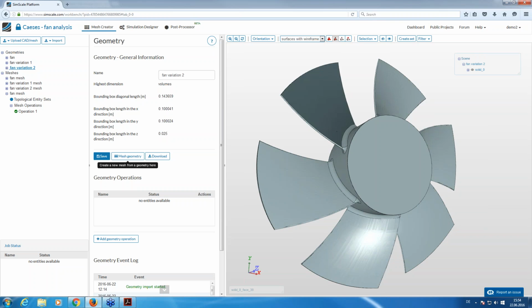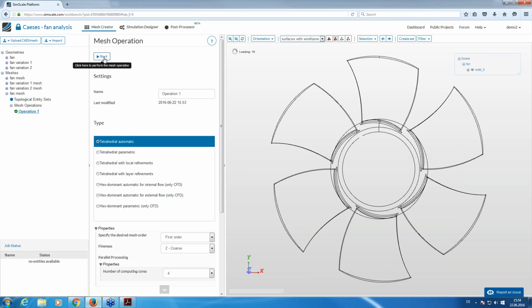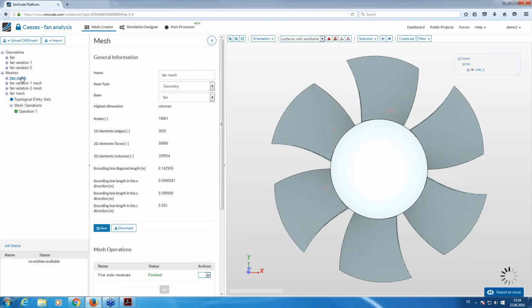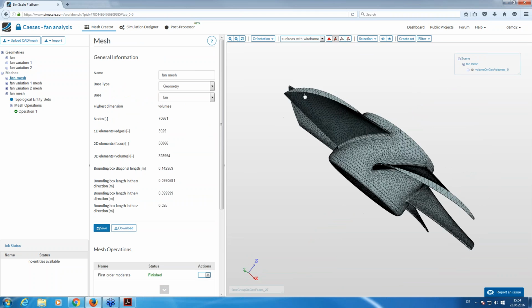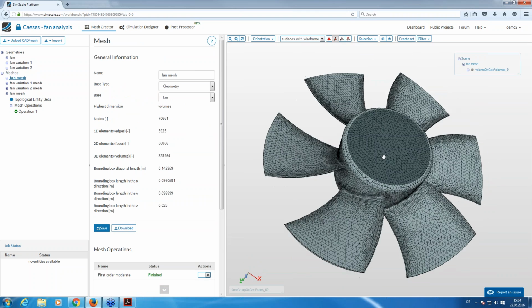You also know that from materials that are stiffer, if you hit them and see the vibration, it will be on a higher frequency. So what we now need to do is simply start this mesh, and what we will get is a mesh that looks exactly like this here, where we see this is now a volume mesh, and we can, based on the nodes of this mesh, start a finite element analysis on this.